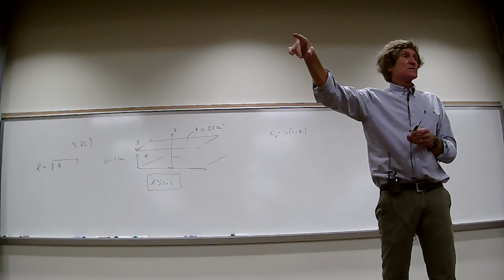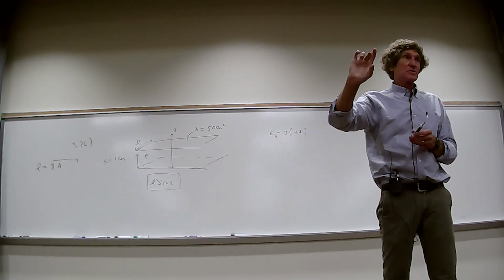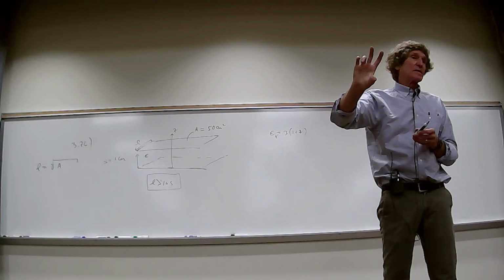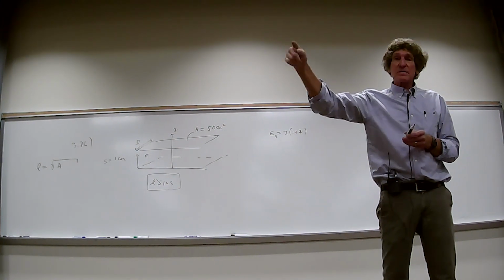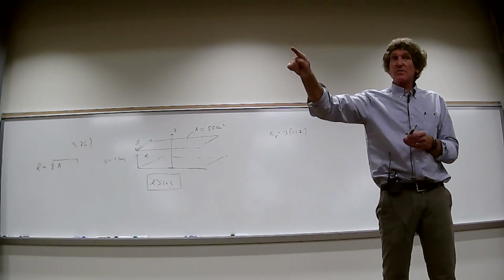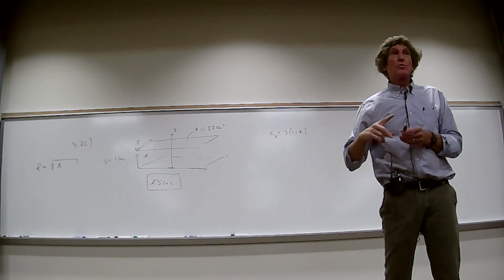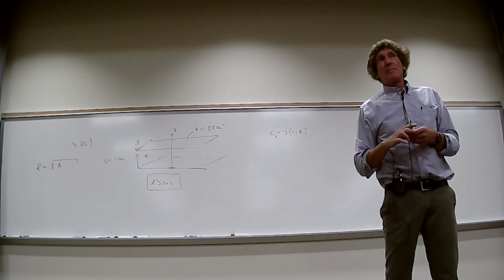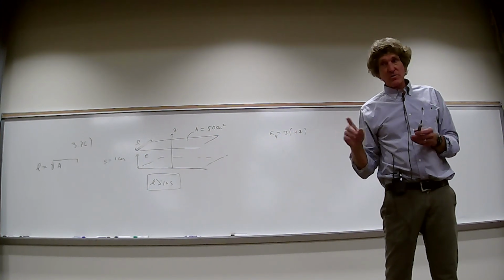So what they'll do is they'll put a big old electrolytic capacitor that will never change its polarity in parallel with the output of the actual full wave rectifier. Then they'll put an inductor in series. Now, an inductor always smooths out the waveform, all right? And then on the end of it, it's called a pi filter. They'll put another large capacitor, but that one's usually not an electrolytic. It can be, but it usually isn't.